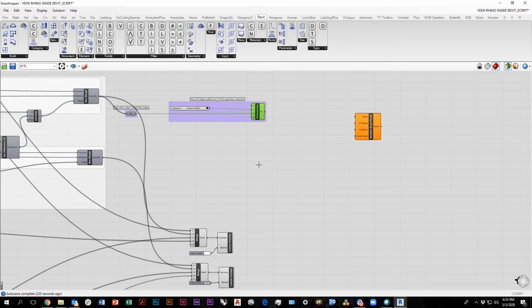Yeah, I've tried to make an asymmetric sort of exploded framing plan. Whenever you build a model in BIM, you're left with just solid massive walls, so you have to custom model it yourself. I would still custom model it myself instead of using a wall and saying this is what it is. If it's exposed trusses, I would build those trusses. But if it had any level of curvature, you're not using Revit to build it. You're using Rhino and then importing it.